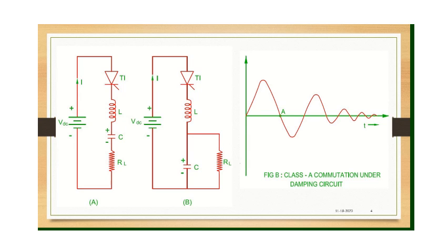With the information on L and C that we just discussed, you might now be in a position to understand. Initially, when the SCR is turned on, the capacitor charges to the VDC level. Once the capacitor voltage is equal to VDC, the current in the circuit will stop, and the inductor then reverses and acts as a voltage source.